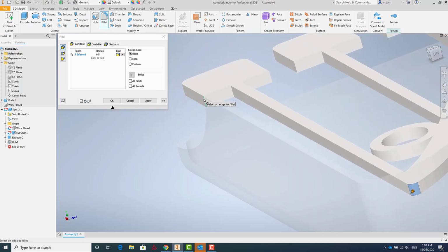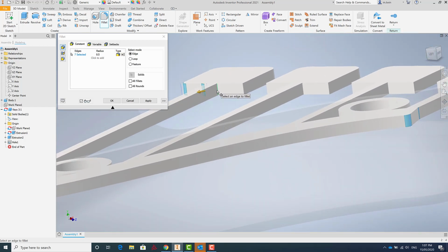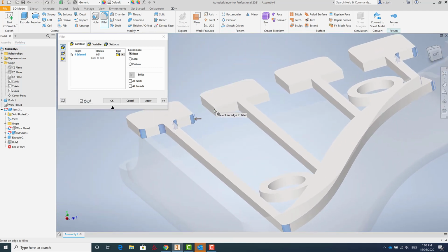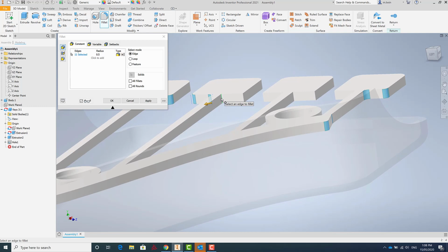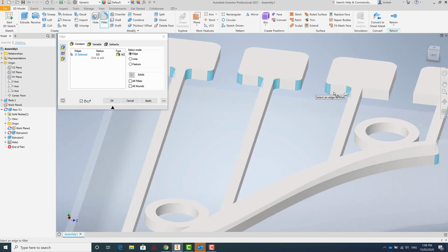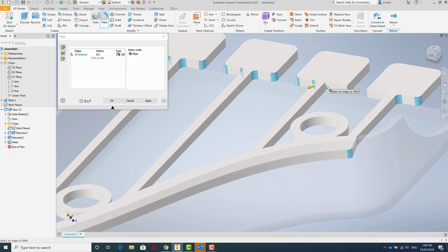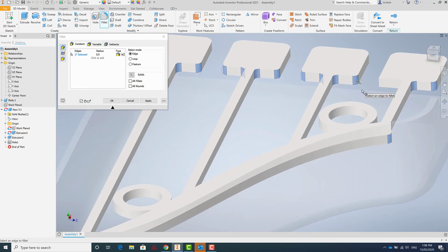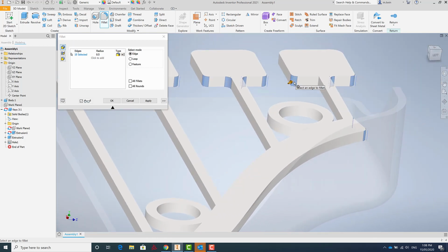And that'll get me a stronger bond, and also means that the water jet, when it cuts these out, isn't trying to do a sharp corner, which can sometimes lead to the jet actually running on a little bit, and it might cut through a bit more of our thin 1mm little arms there, and we want to keep those as precise as possible.